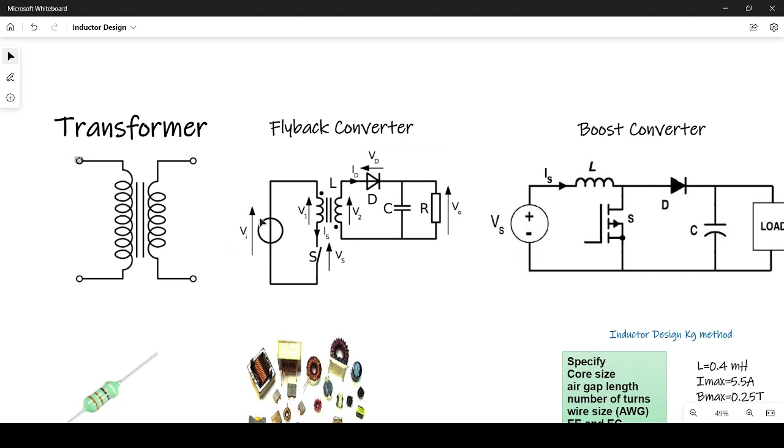like the DC source. The problem here is you want to change this voltage or get pulses from this DC source to this coil, like you want to trick this transformer to play on it like you're producing an AC, but it is not an AC, it is a unidirectional changing magnitude voltage, and you induce on the other side, on the secondary, another voltage, and you try to rectify it and filter it to get it to your load. So you try to step up or step down according to the turns ratio.